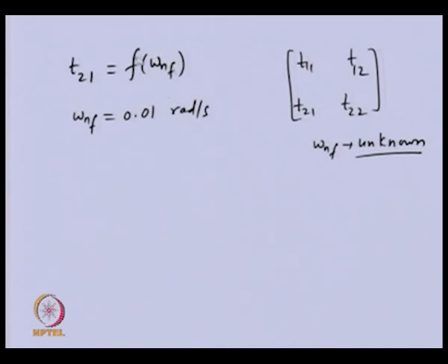So we don't expect that at the first initial guess this will be satisfied. There will be some residual, and obviously then we need to take an increment in the assumed natural frequency. That increment can be further less depending upon the accuracy we need.